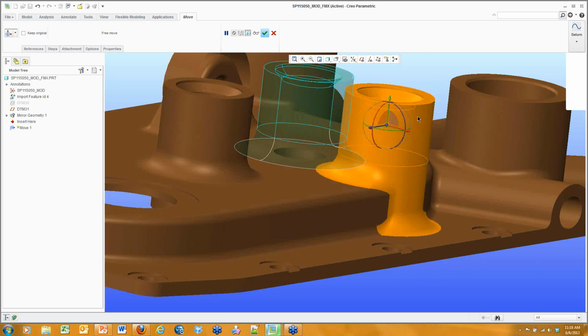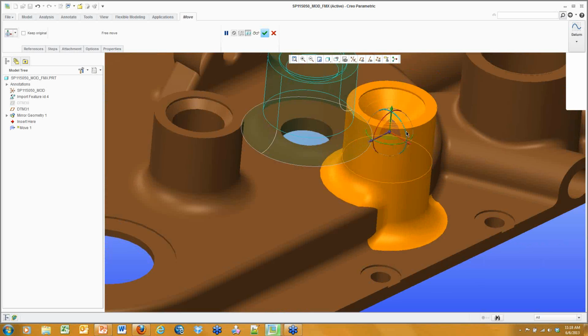Creo Parametric is smart enough to realize that with direct modeling, this is just a cylindrical feature. And even if the cylindrical feature just comes off the edge, the cylindrical feature is able to complete its regeneration. In fact, we can come in here and say, well, now it has to rotate a bit.